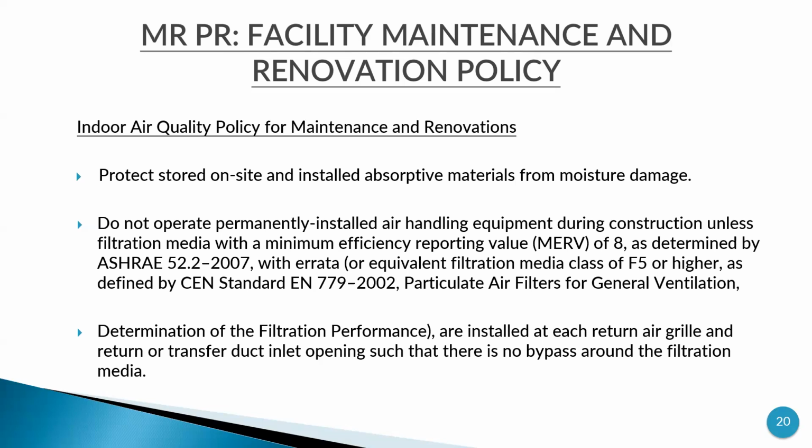Filtration media with a minimum efficiency reporting value, MERV, of 8 as determined by ASHRAE 52.2-2007, or with a rating of CEN standard EN 779-2002. So is that the centralized AC? Wherever the filters are used, generally in ducts and AHUs.